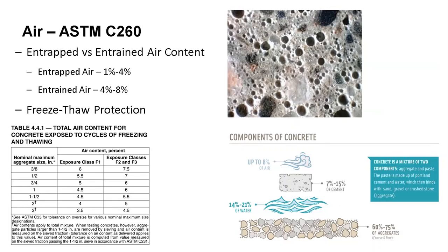And anytime we have freeze thaw, it's important to add this entrained air. It creates a path for the water that's naturally in concrete to expand into and prevent it from causing the concrete to crack and to basically explode on you.